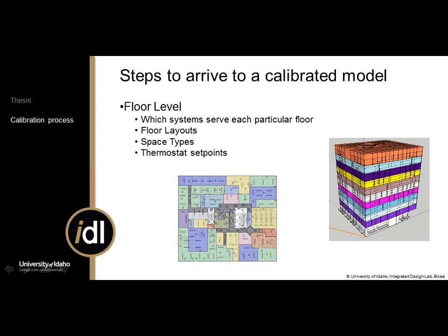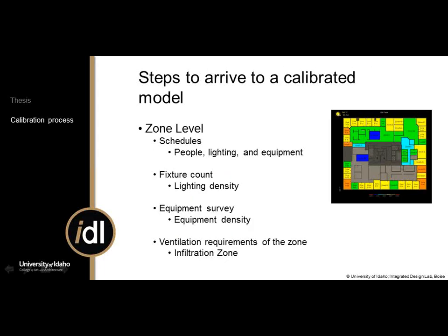In smaller buildings, you can probably talk to the tenant to check out the individual thermostats. But I was able to get set points from the energy management system as well, and took an average for the whole floor, because defining 665 thermal set points for the entire building was going to be time consuming, and there's no relatively easy way to do it in a simulation software. Can I ask a question?